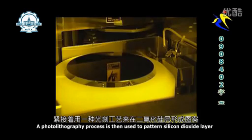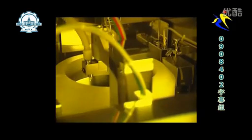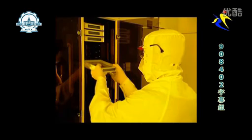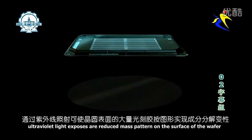A photographic process is then used to pattern the silicon dioxide layer. Photoresist, a light-sensitive material, is evenly spread across the wafer. Inside an exposure system, ultraviolet light exposes a reduced mask pattern on the surface of the wafer.